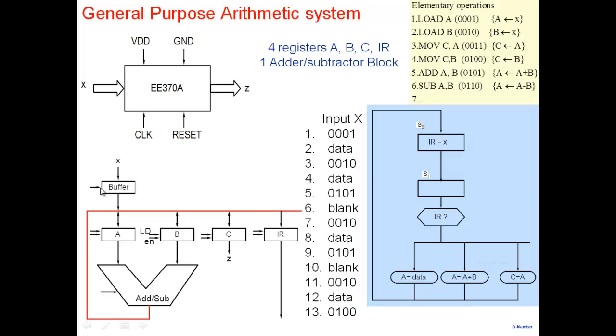Yeah, I enable this and I enable this also. So once this signal comes in, this is available here. So in state S0, this will be enabled and this will be enabled. At the end of the clock edge that we said, as it exits this particular state, the clock edge will latch those things. So the actual latching will occur at the end of this particular state.